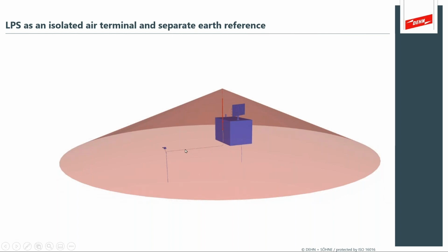But we're using isolated materials to put the earth rod far enough away from the actual earth rod of the structure to prevent that ground potential rise. So we're trying to prevent direct side flash. We're trying to prevent GPR. We're trying all those mechanisms that we thought we were worried about, we want to protect from. So we're reducing all of the mechanisms that want to induce surge currents and voltage transients.